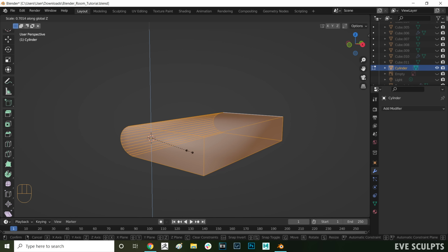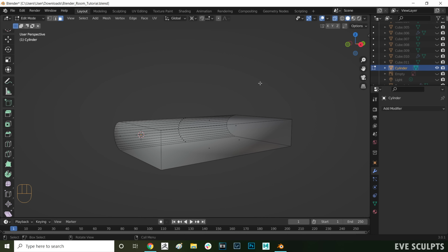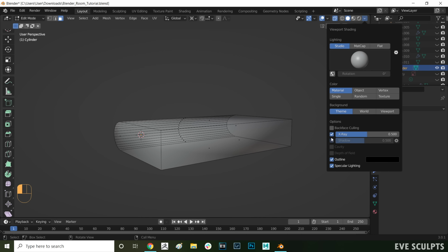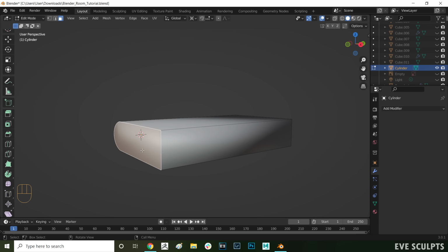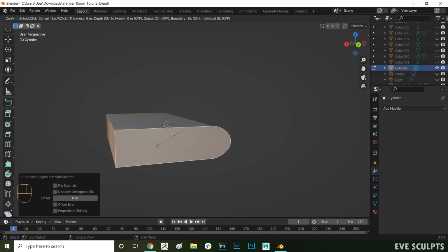Now we want to extrude in to make pages. Press 3 for face selection. Select the inner faces of the book we just created by clicking on them while holding down Shift. Press I to make inserts of the faces. Click to accept the insert.